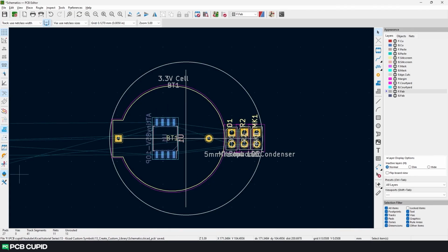At this point, I want you to remember assembling components on both sides of the PCB can be cumbersome. But it's still doable if you are doing it for a small quantity and you are doing it by yourself. However, during large production, it can increase the cost significantly along with the complexity of the PCB. Therefore, opt for two-sided assembly only if it's necessary, or stick with one-sided assembly. In this case, I'll convert most of the components to SMD and place all of them on the bottom side of the PCB.